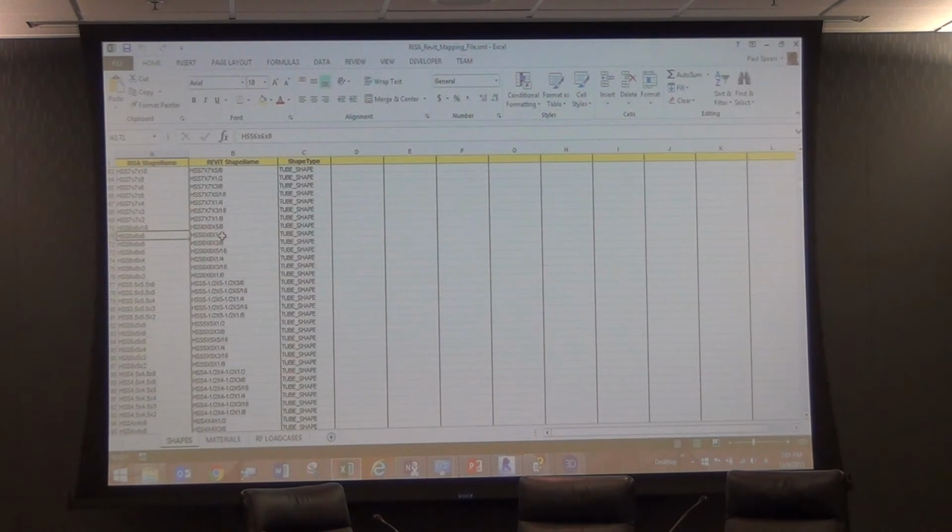So another one, and this is probably even more critical or crucial, is dealing with bar joists. When you have point loads on them, RISA will design them and call them SP joists, which they should be, but there's no such thing as an SP joist in Revit. So when you try to read it back in, it's going to be incorrect in finding that joist size.